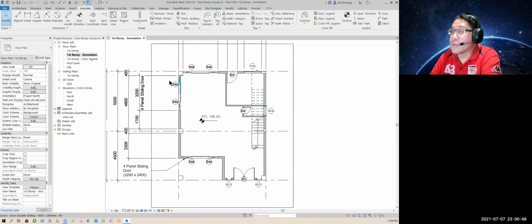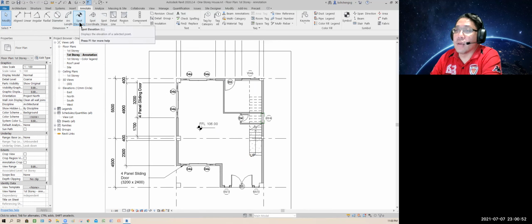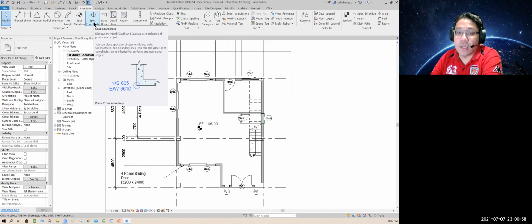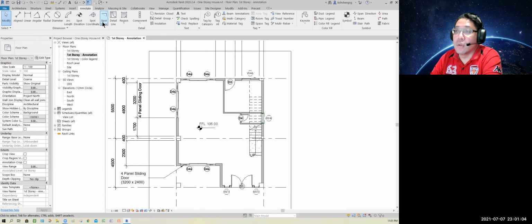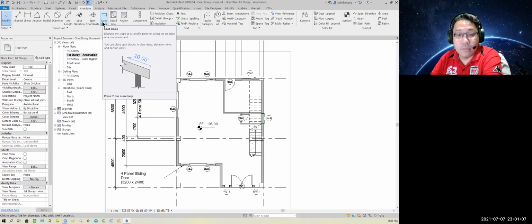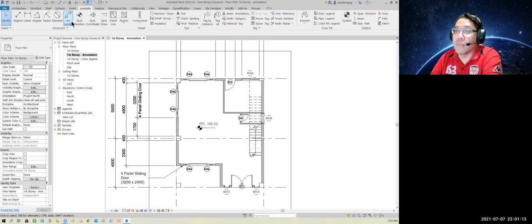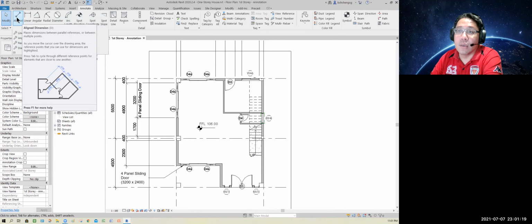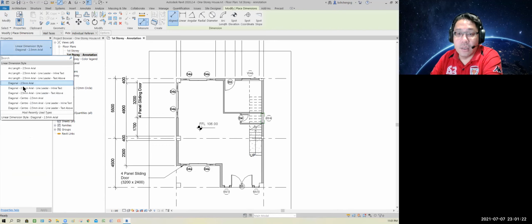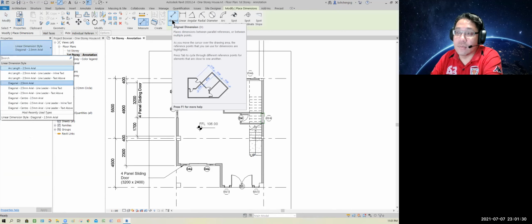Okay, so the other option is for elevations, which we have done. This is spot coordinates. Unless you're a surveyor who wants to know coordinates, you do that. If not, this is for slope, at elevation, not on ramp, on plan, no. Other settings for other dimensions you can get from here. It's just that when you choose align dimension, the setting is always by default at the type selector. The rest are not here because in Revit, this is the most widely used function.